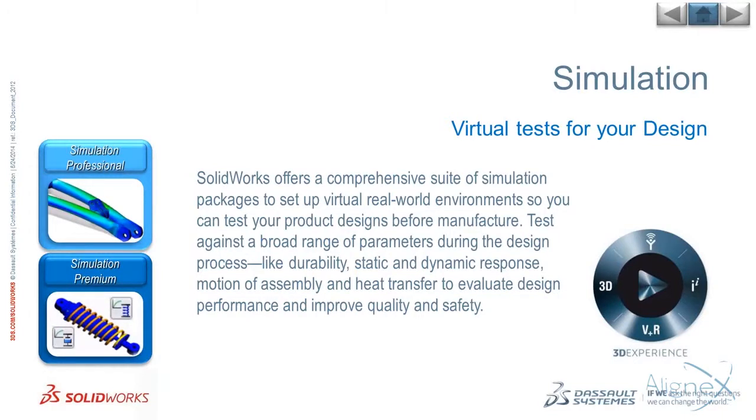So as most of you already know, SOLIDWORKS simulation allows us to run linear static analysis and motion analysis. The main difference between these two is the type of solver that is used. The linear static solver allows us to investigate deformable bodies. These are simply bodies that can deform or change shape under some loading case. So this type of analysis allows us to predict things like deformation, stress, and reaction forces of a structure.